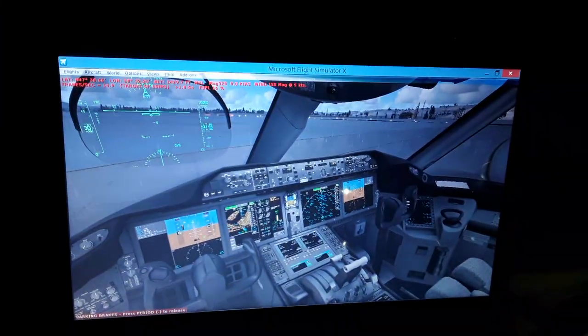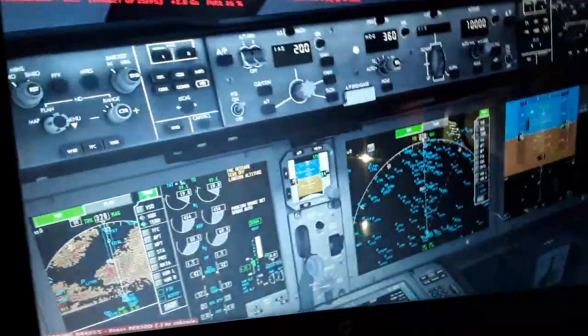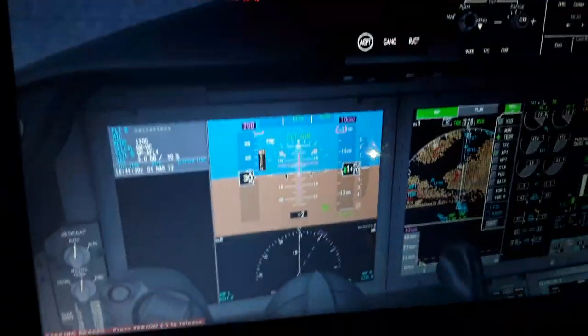That is 23% of the forward wings, the position where the maximum aerodynamic lift occurs in the forward wings. It is the position also where the stall will begin as we fly. The airflow will become detached from the top surface of the wings, and the aircraft may start to stall. Also, we need to monitor over here, we have the airspeed. We have to monitor all the time that the airspeed is always above the stall speed during flight.